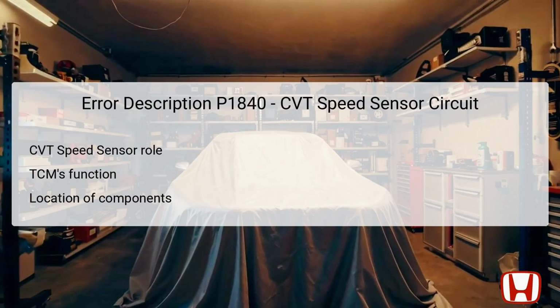The CVT speed sensor is an essential component that measures the rotational speed of the secondary shaft in the continuous variable transmission system. Located typically near the transmission assembly, this sensor ensures that the TCM receives accurate data regarding the rotation speed for efficient gear shifting. The TCM acts as the brain of the transmission system, processing input from various sensors, including the CVT speed sensor, and governs the operation of the transmission based on this data.